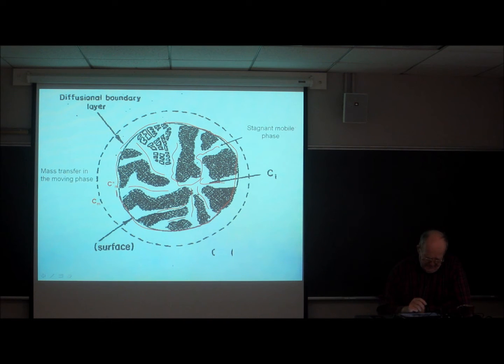Now, transport outside of the particle, here in the moving phase, since that phase is moving, part of the transport mechanism, at least part of the transport mechanism, is convection. Once a molecule arrives at the outer surface of the particle and enters a pore, there's no longer any convection.